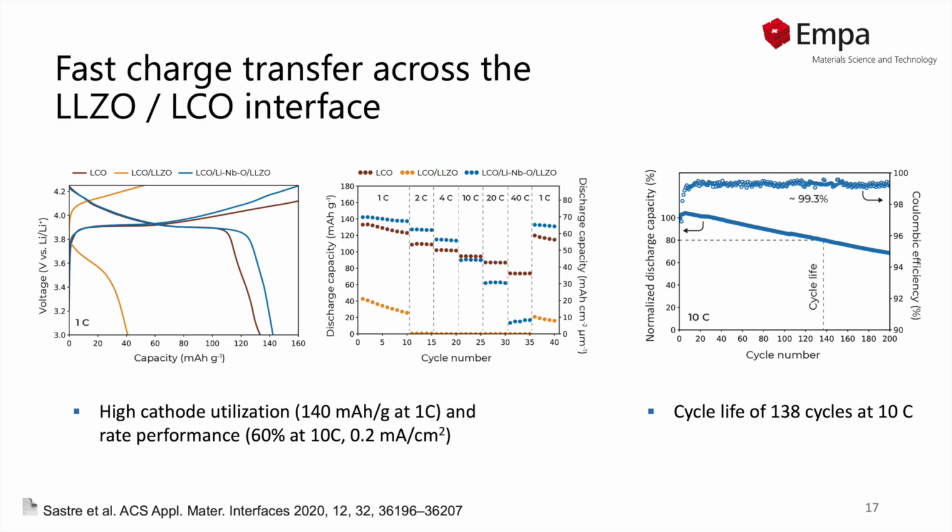We also assessed the cycle life performance of these half cells. We cycled them at 10C over 200 cycles and observed a cycle life of 80% initial capacity retention of 138 cycles. This is significantly higher than typical LLZO solid-state batteries reported in literature.